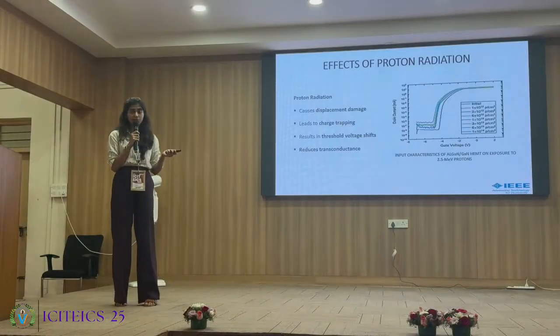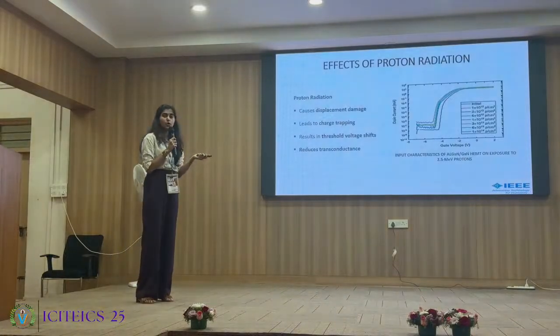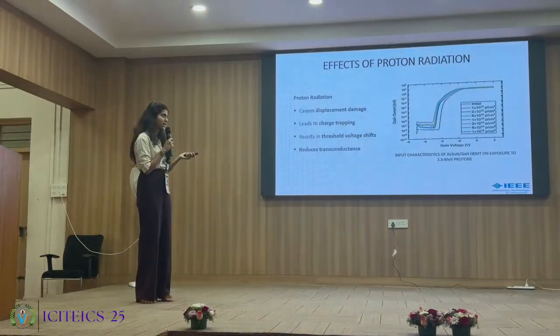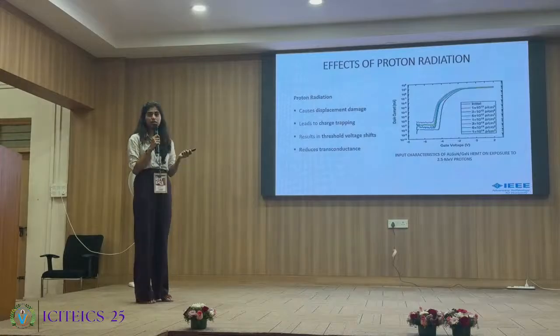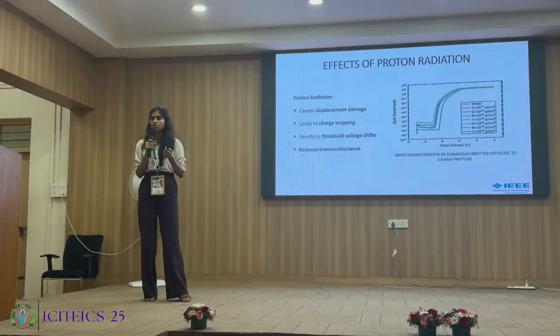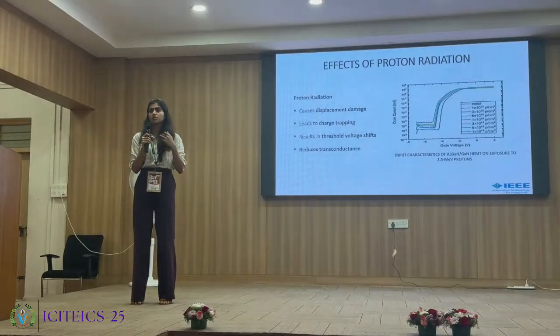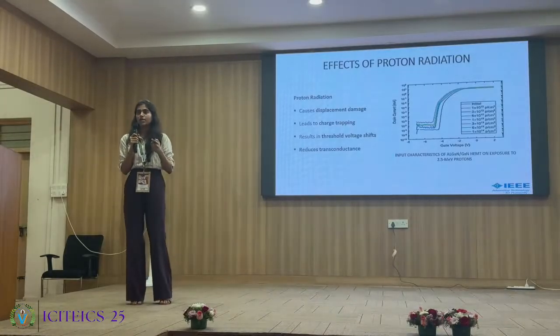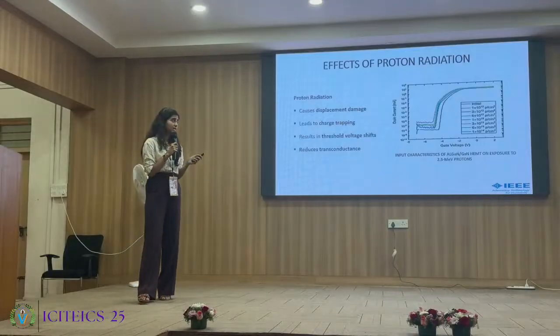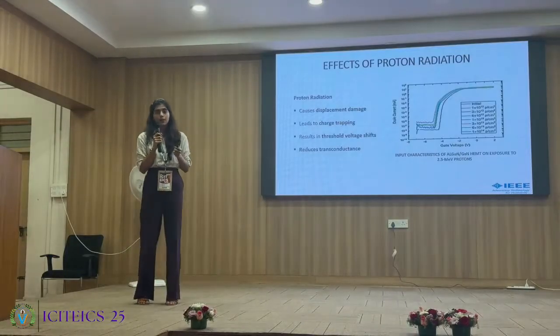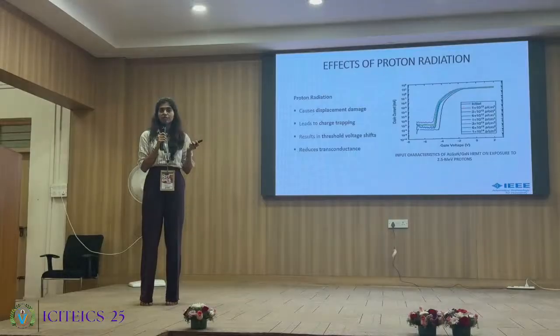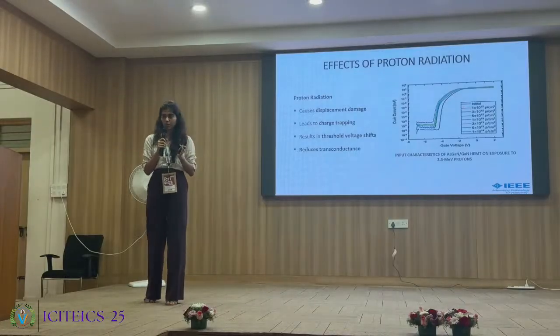Following irradiation, the devices show an initial increase of the gate leakage, followed by a simultaneous increase. You can also see an increase in the drive current, which is the drain current for gate voltage above the threshold. So these results suggest that single event burnouts will occur at a lower breakdown voltage.